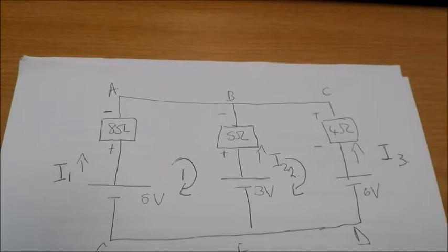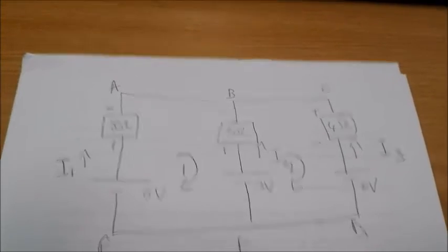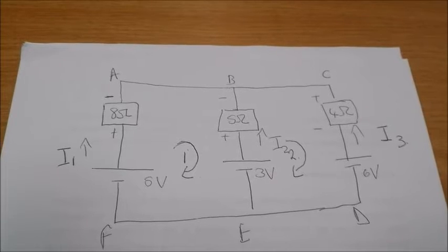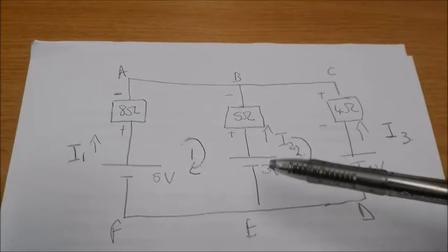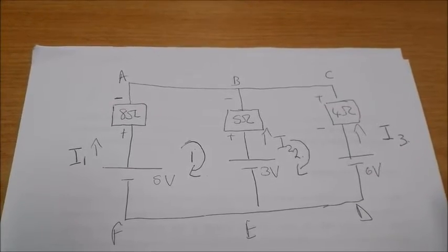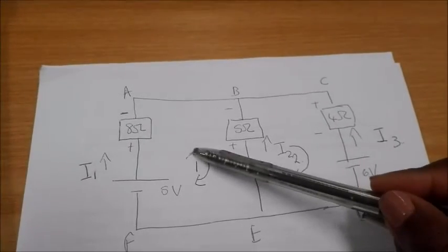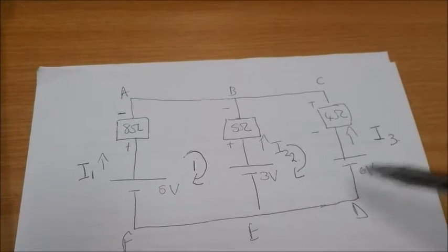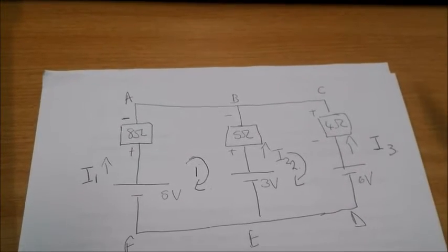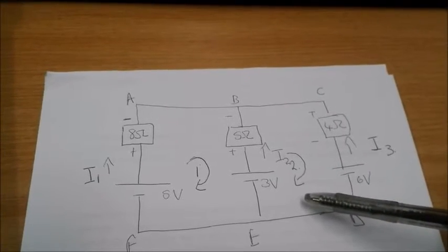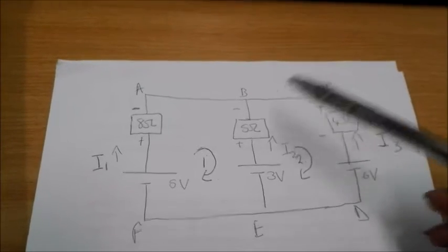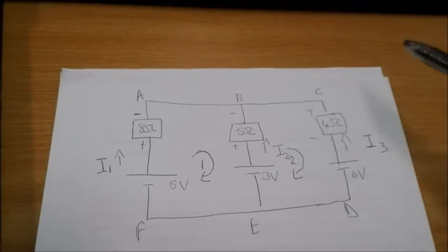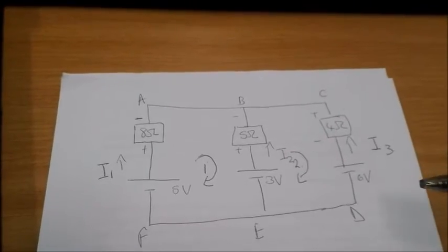A loop is obviously something that's a circle, and it indicates direction. As you do this course, you'll realize, number one, you can do this direction either clockwise or anti-clockwise. However, you have to have continuity, which means if you name this loop 1 and say loop 1 is going in a clockwise direction, then in the entire circuit, be there more parallel cells or other cells, you have to indicate it in the same direction that you've chosen for the first one, so that you have continuity and it all is the same. Thereafter I just put in current 1, current 2, current 3.